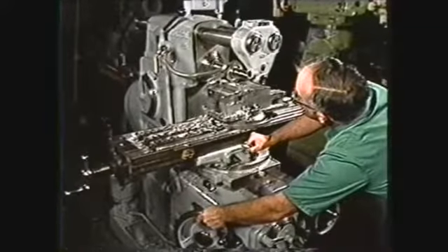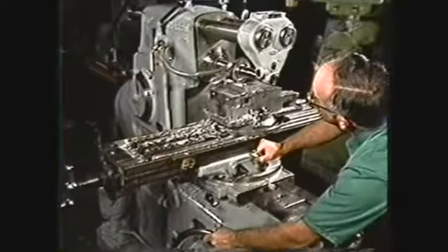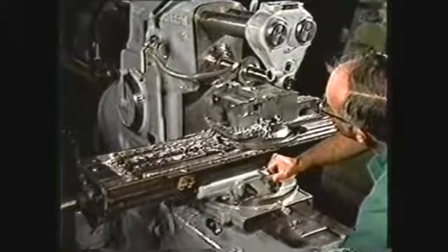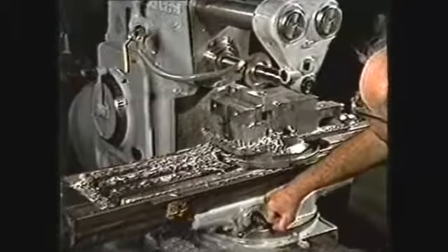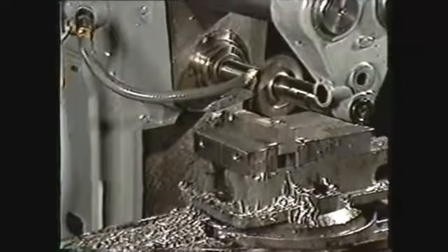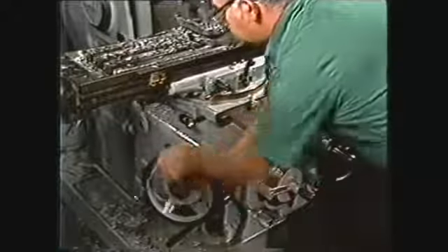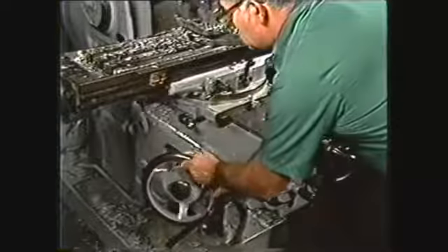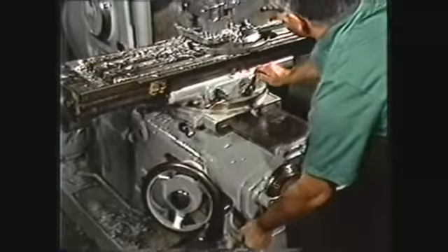A good depth of cut for a side milling cutter is between 100 and 200 thousandths. Pick up the cut on top of the work. Move the work from under the cutter and take the depth of cut with a vertical hand feed. Engage the longitudinal power feed.